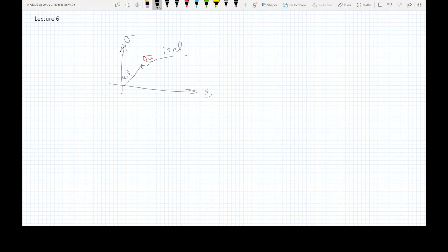And we said this is the failure point for us as civil engineers or structural engineers. This is the point which defines failure, and beyond this point, we would consider our structure has failed. Now, we realize that this is only possible if we have stress active in one direction. So in the uniaxial test, if you are applying tension on a steel bar, you have stresses happening in one dimension, and the stress tensor is going to look like this.